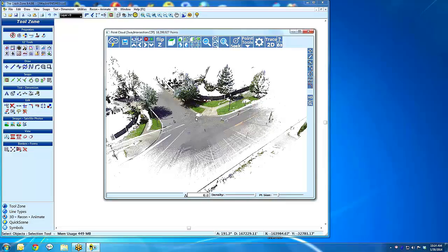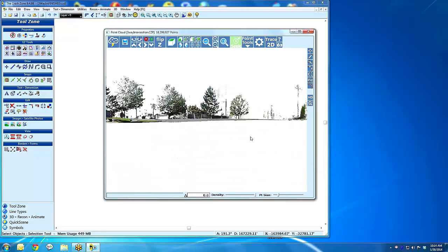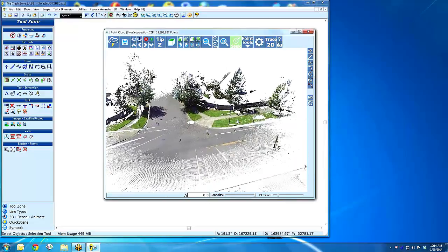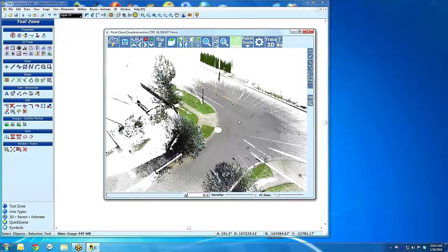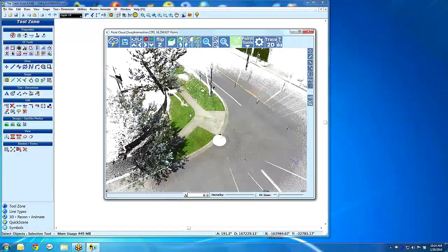So the neatest tool we have for doing that is Seek. And this is kind of the king of the navigation tools. You click on Seek, and you pick the area. This is really setting a rotation point. You click, let's say, right there. And once I do that, everything I do revolves around where I clicked with Seek. So I can rotate, but you notice it's zeroing in around that.